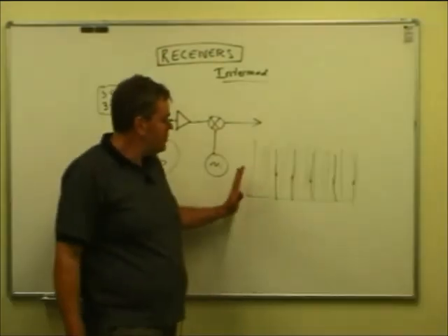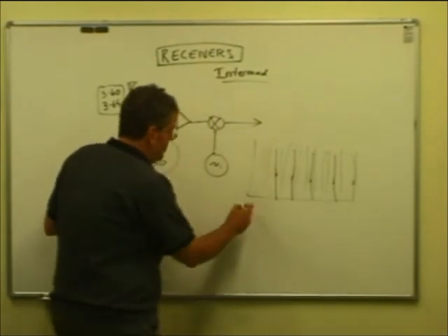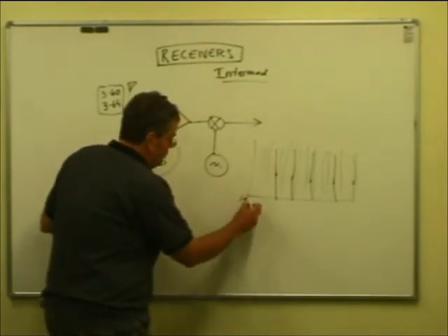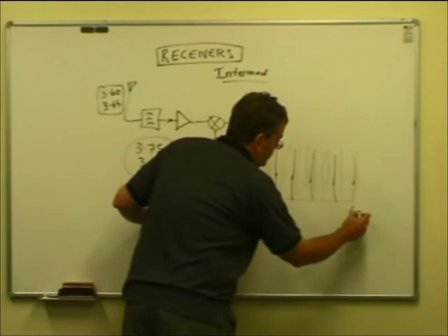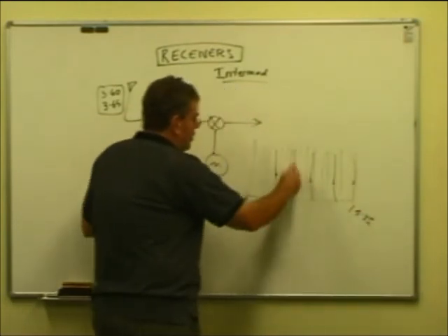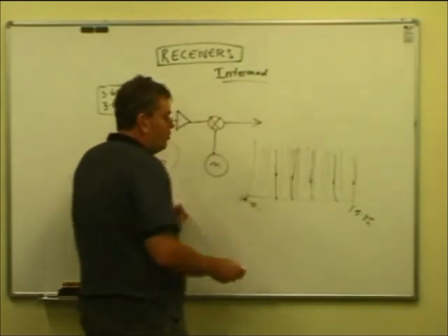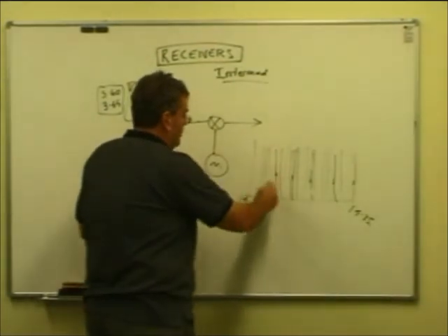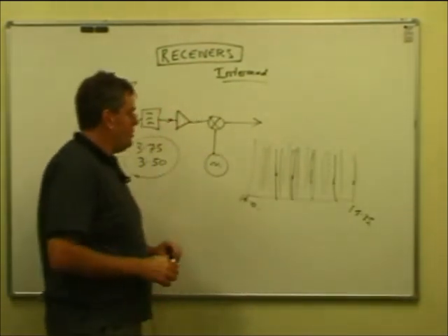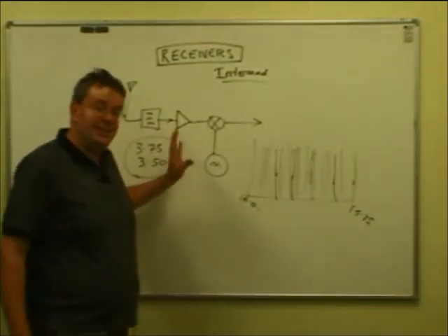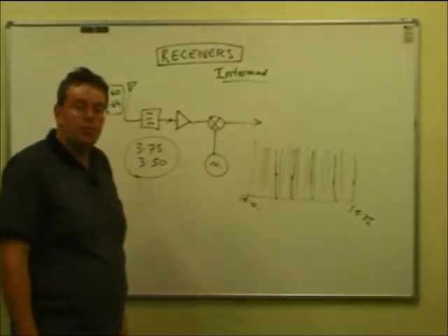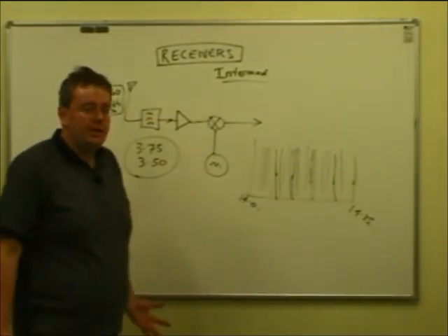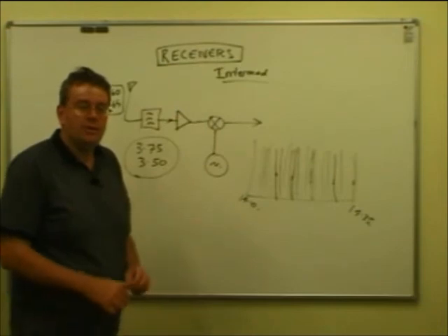And that's what would happen on, say, the 20-meter band, running from 14.0 to 14.35. If there's a whole lot of strong signals around, then all of a sudden these other signals will start appearing. And all it is, is signals created in the front end of your receiver because of poor receiver design, and it can actually make your whole receiver unusable under those conditions.